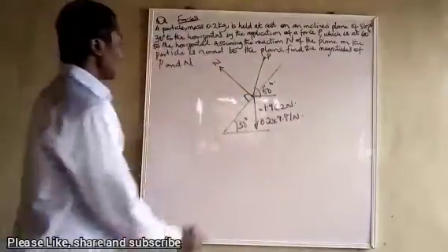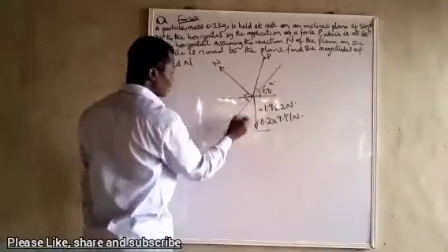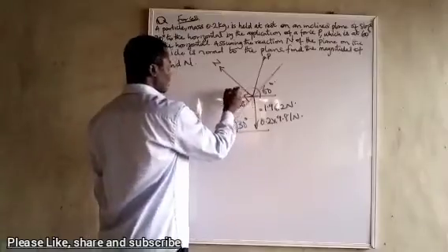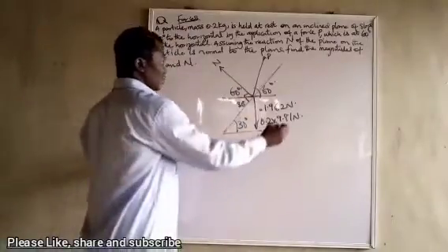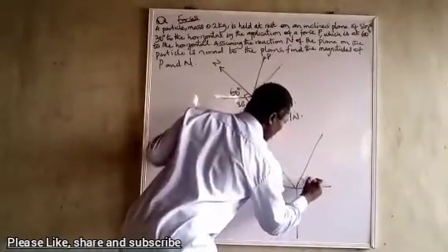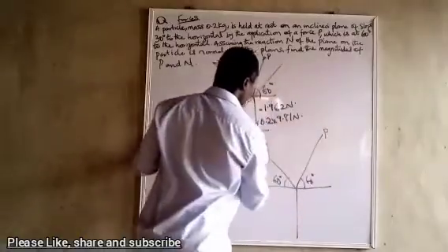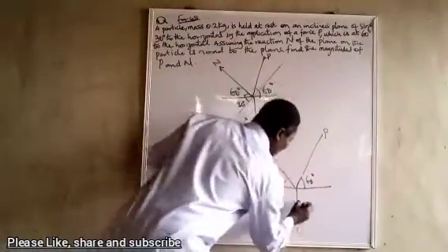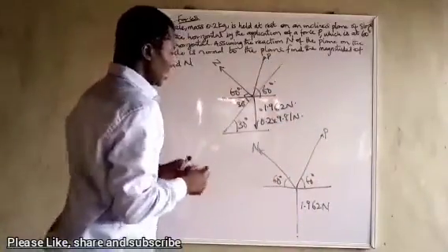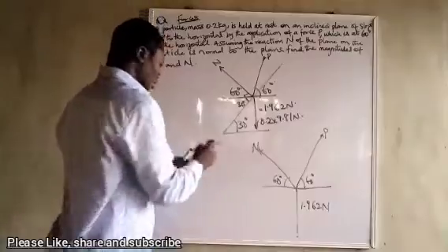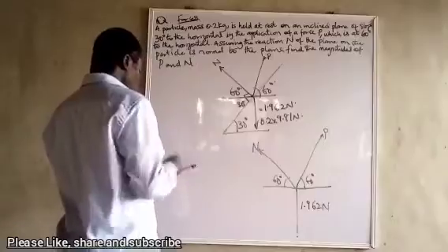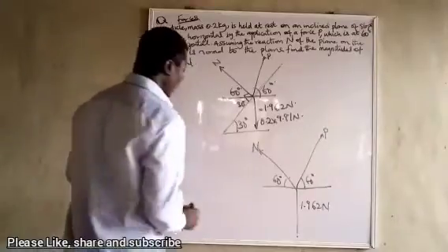So you can see, let us find the direction of this N to the horizontal. This place and this place is 30 degrees. And everything here is 90 degrees. So this place will be 90 minus 30. This place will be 60 degrees. So we have a first situation like this. So we have 60 here, 60 here, P, N. That's it. And we have 1.962 Newton here. So P goes here, N goes here. We can use triangle of forces to complete it, or resolution of vector, and just make it like a vector notation. So let's just use our diagram first.